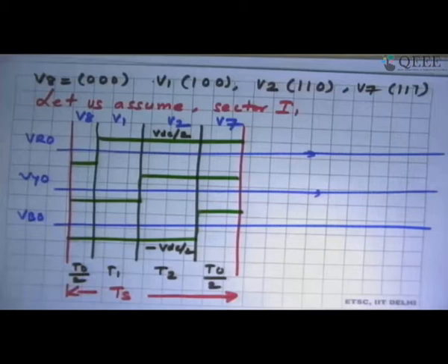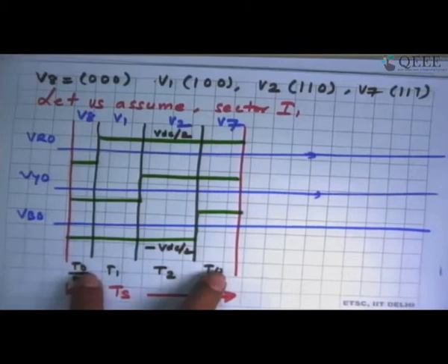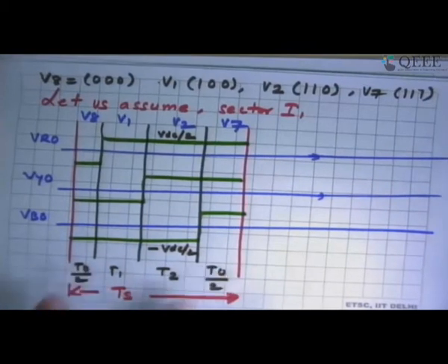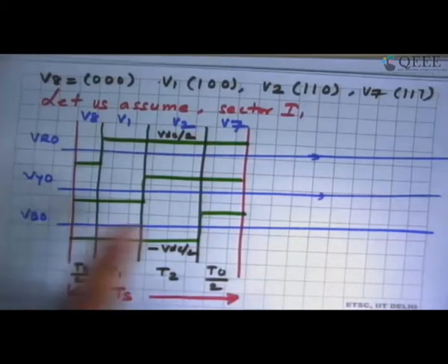So this is a method where you apply switching vectors to get the resultant, depending on the sector you belong to. The active vectors will vary. The zero vector time more or less will be divided into half here. Why? So that there is only one transition in each phase.